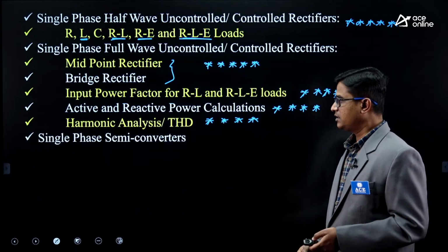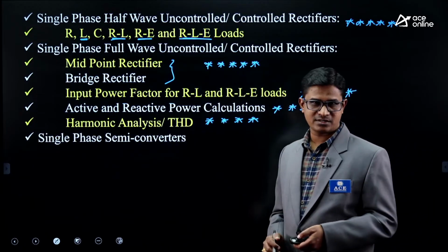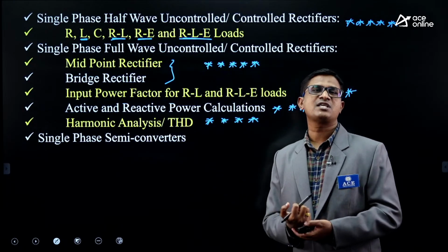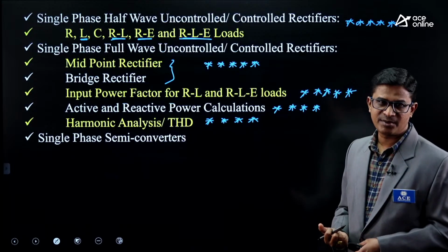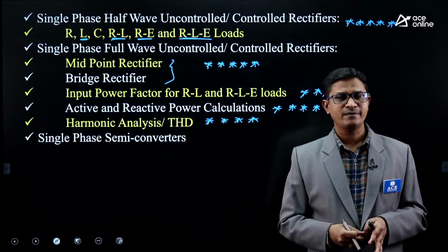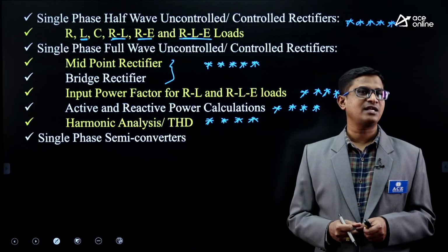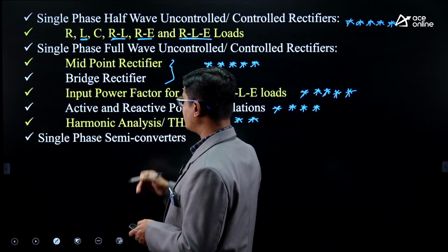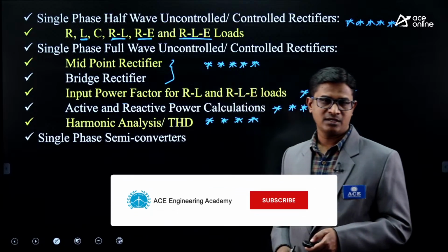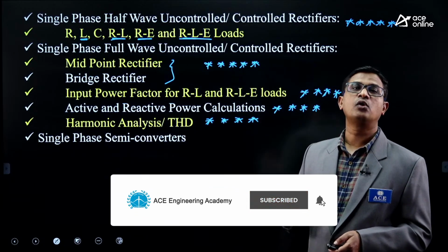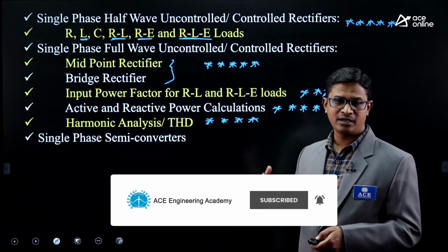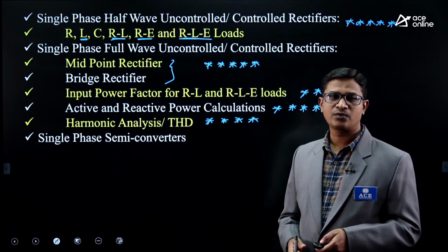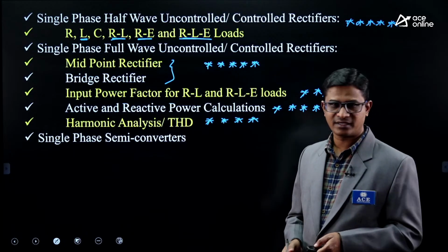Next, single phase semi converters. Like single phase half wave, single phase full wave, we have the single phase semi converters. Single phase semi converter is a bridge circuit where we use 2 thyristors and 2 diodes, etc. So you will find some questions related to the single phase semi converter: output voltage expression, load current, what is the input power factor, real power input, what is the reactive power input, etc.